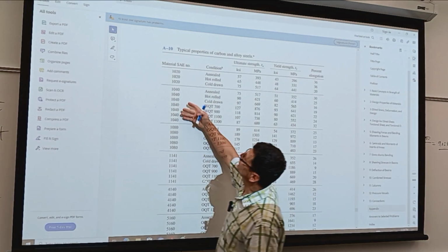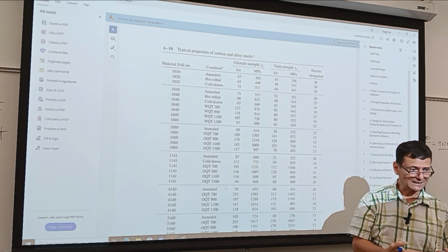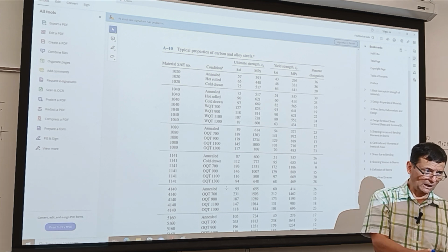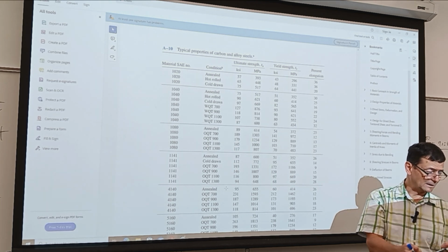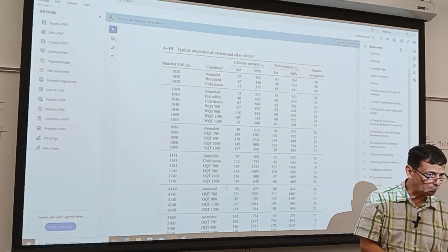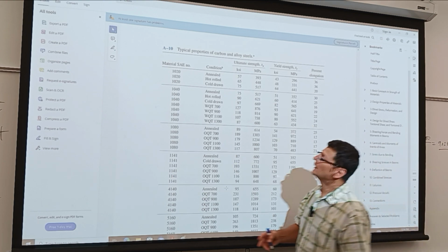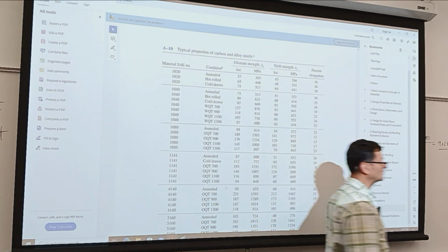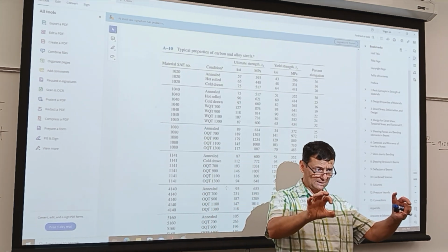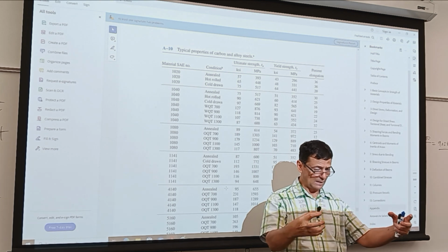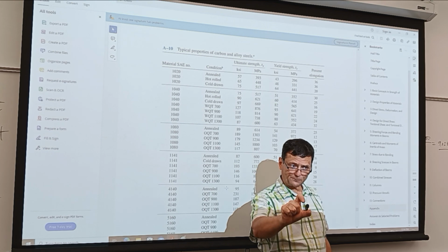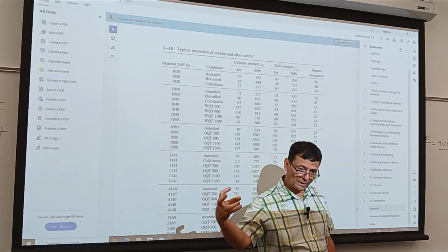And by cooling them slower, they're less likely to warp. You remember from material science, hardening comes with phase change, and phase change means a slight volume change, and because of that they can warp, particularly thin areas. So there's geometry change after heat treatment. You need to do one final machining, grinding the areas that you need to control. Say you have a shaft with a bearing that needs to go on certain areas. After heat treatment, that diameter is slightly different than before, usually bigger, and you might not be able to run the bearing.